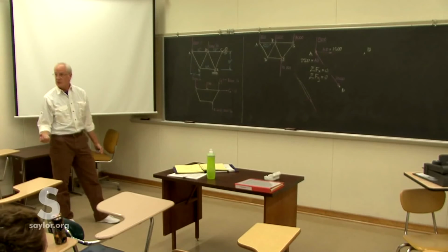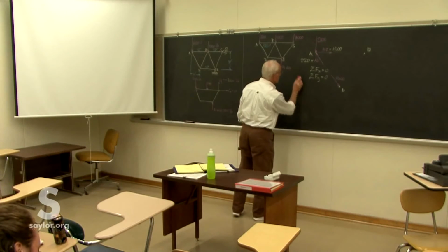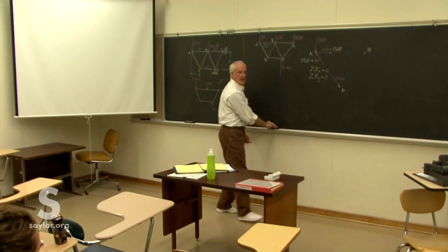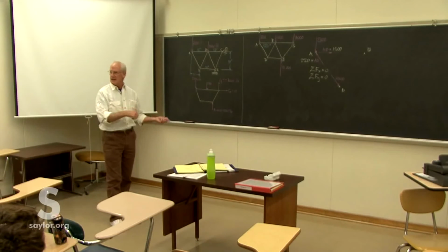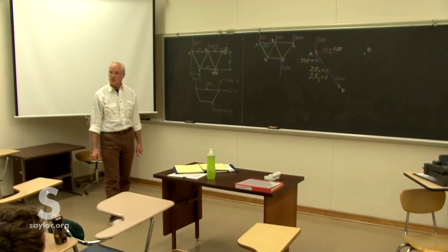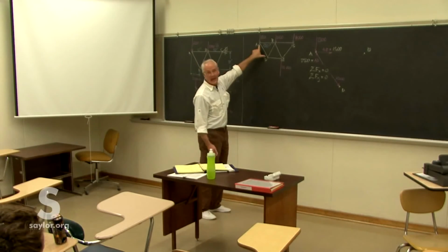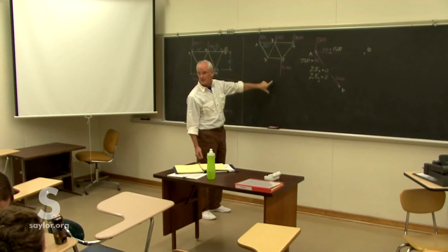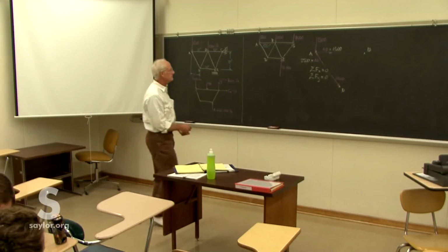Now, that's important to us, because one thing we could decide anywhere along the structure, if we were the designers of it, is if we have a member in tension, maybe we can take it out and put in a cable. Be a lot lighter, might be a lot cheaper, and if it's only going to be in tension, a cable can take tension. A cable cannot take compression. So we would want to put a cable in here and stand under this thing. You might want your boss to stand under it, but you don't want it.